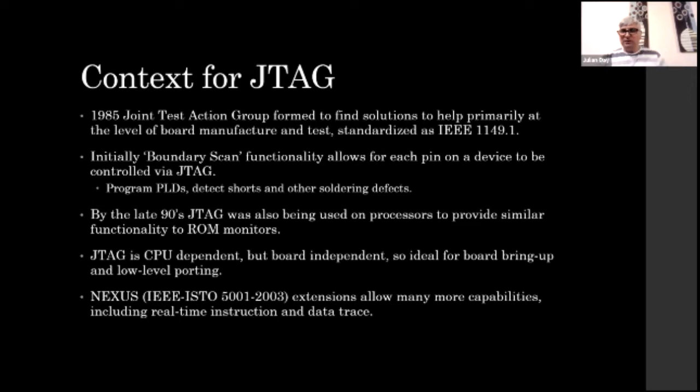It became more and more difficult to work out, if the board didn't work, why it didn't work, and conversely, if it was going to work by the time it reached the customer. And so this action group, JTAG, was formed, and they came up with the standard IEEE 1149.1. So JTAG and that standard are referred to synonymously.